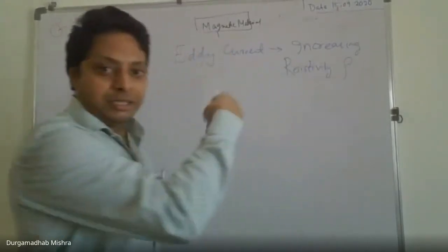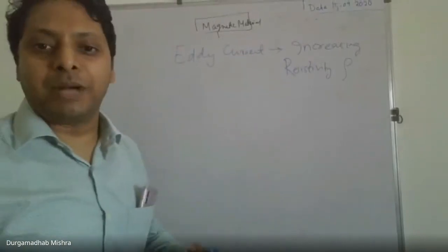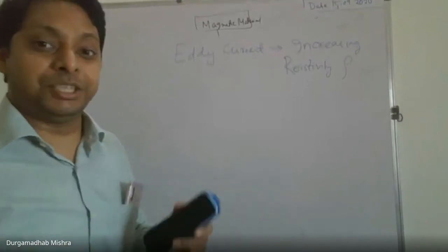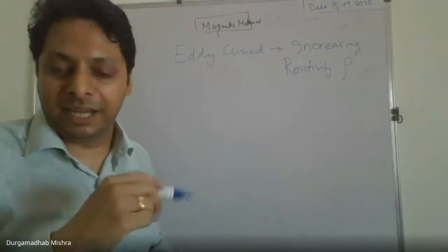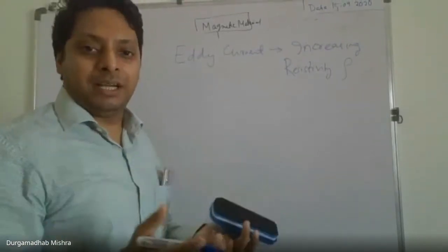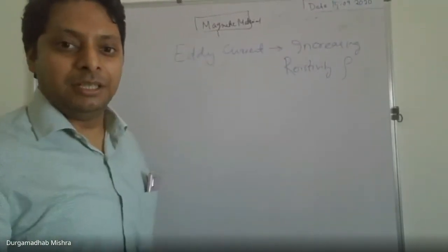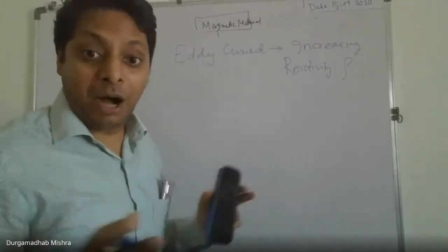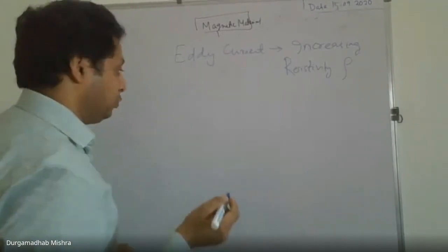So most of these materials which I wrote are metallic, so they are better conductors, right? So the resistivity is low. That's why you will always have an eddy current loss due to that. But if we can make a material with a very high resistivity, then you can practically forget about the eddy current loss. And such kinds of materials do exist.